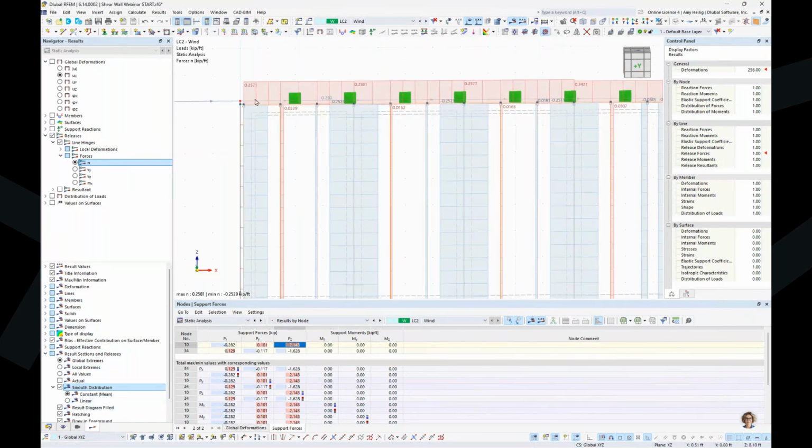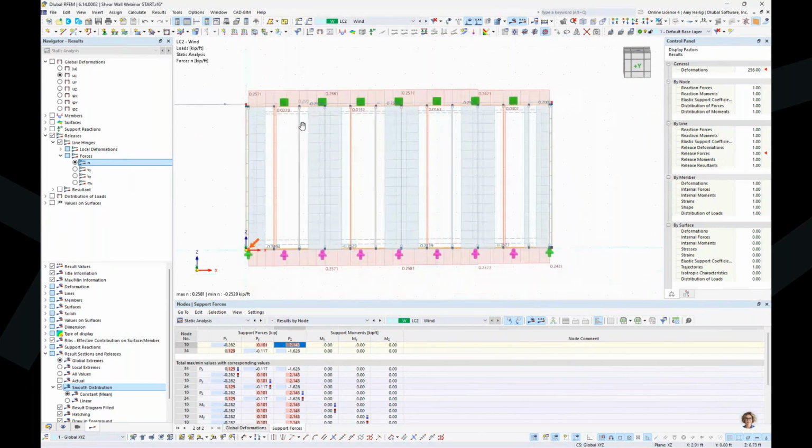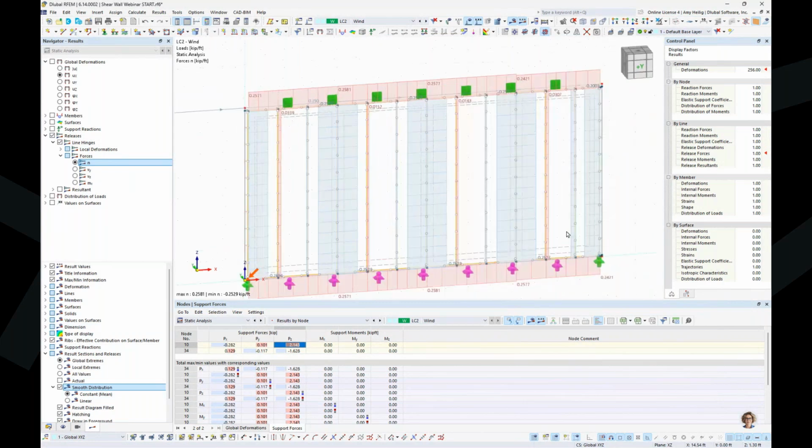Now, it's not exactly 0.25 kips per foot because we don't really have an ideal shear panel here when we're talking about hand calculations. When we look at hand calculations, we're really only considering the end studs. We're further not considering the inner studs here. We are also not considering these nonlinear equations, essentially for the slip of our connections.